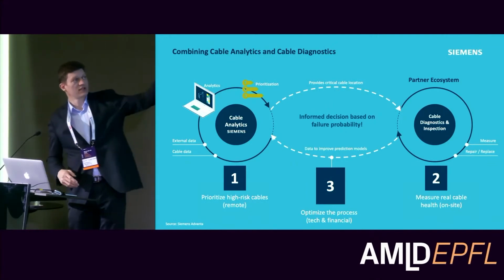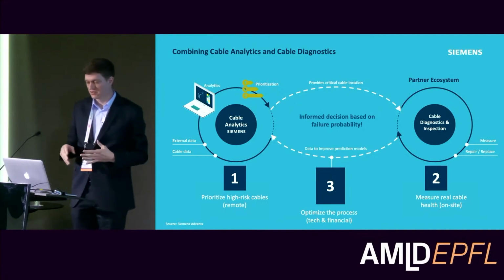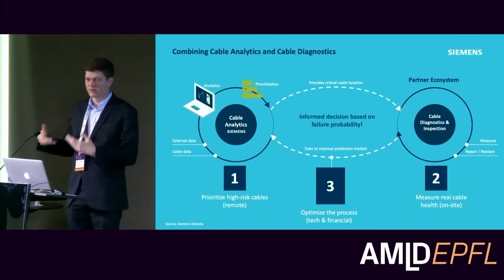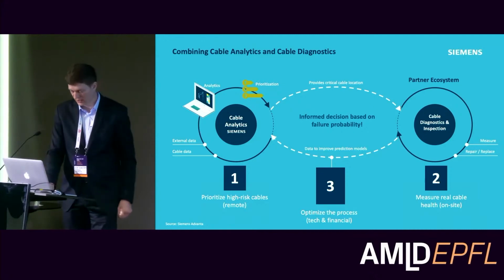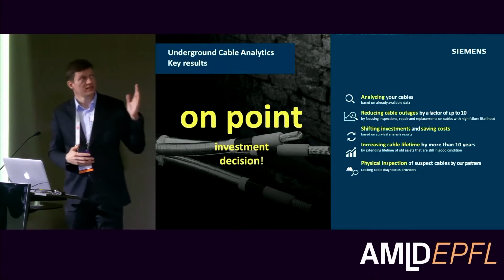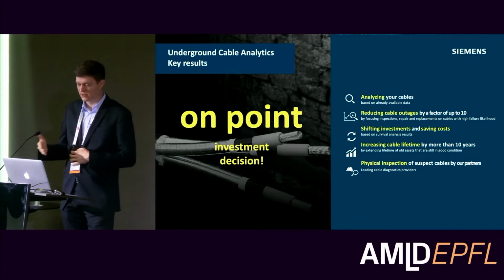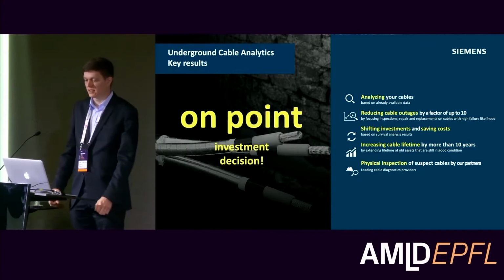Our solution is now being extended with some cable diagnostics and inspection. So we not only prioritize the planning for the maintenance, but also gather new data with diagnostics, with online and offline sensors, to improve the model best with new measurements. So these are the key results: we can analyze the cables quite well, reducing the outages, shifting investments to save costs, increasing the lifetime, and also optimizing the diagnostics efforts.